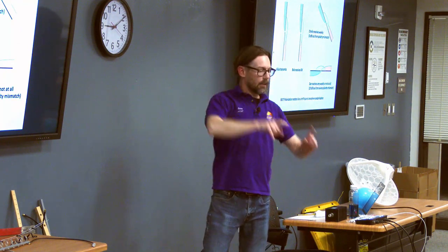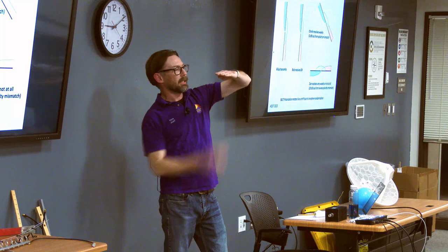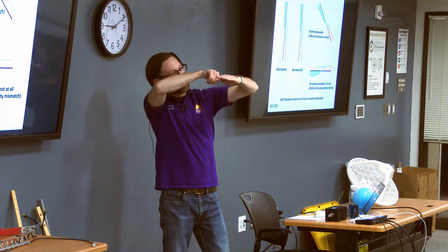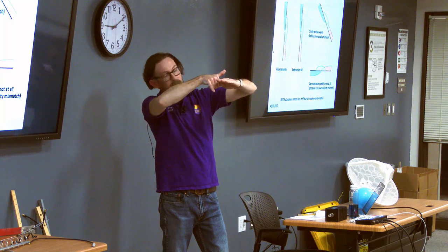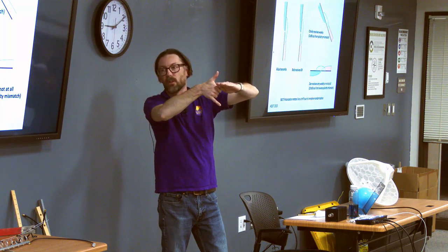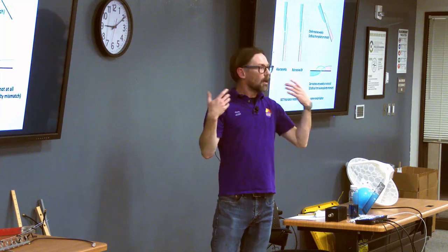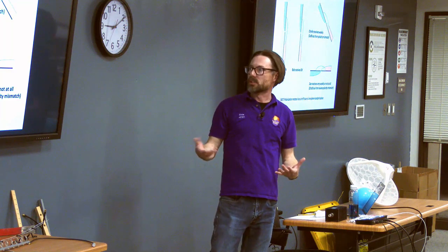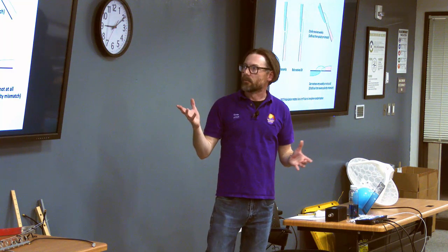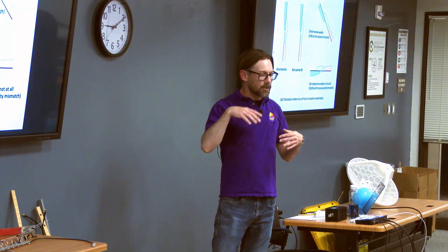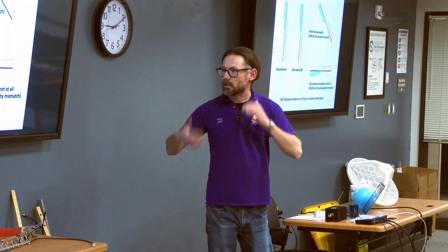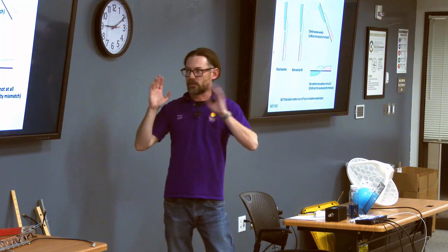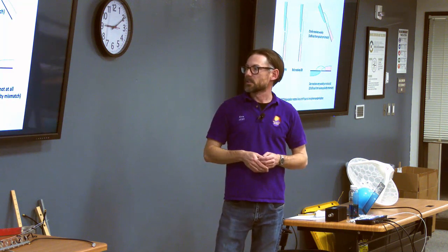Because as we have stuff in this plane, we have stuff in this plane. As we rotate between them, we lose one, but we're gaining the other. And we hit this 3 dB crossover where we start to pick the other one up. So if we are cross-polarized, we have a compromised polarization that works pretty well for everybody. You're going to be 50% down on your power from what you theoretically could if your polarization matched, if you were both vertical, but 3 dB is fine in most cases.